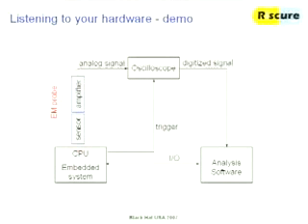So now we switch the setup. And I'll quickly explain what this is doing, because we need to boot up the test program again here. I'm now putting the probe, as it is shown there, directly above the CPU, while it's attached to a battery to reduce noise, and then again to the oscilloscope.